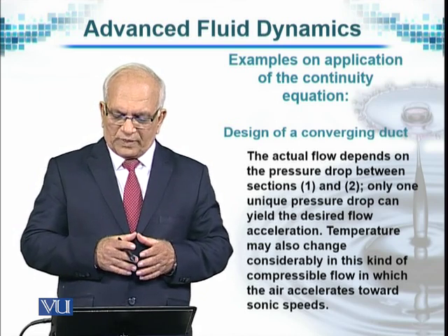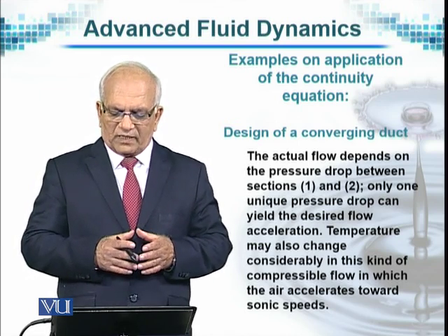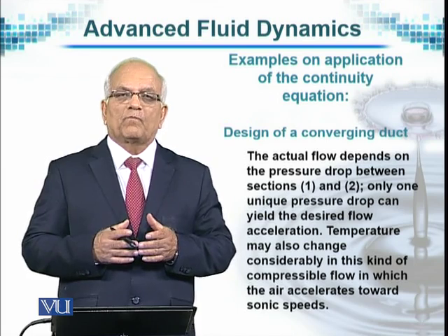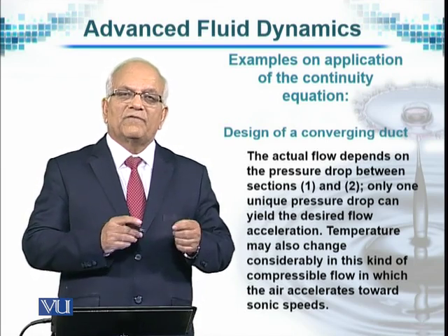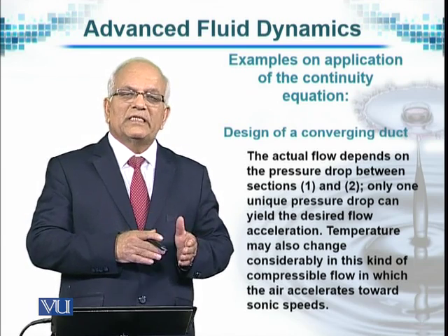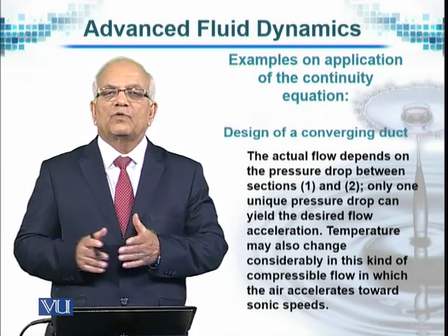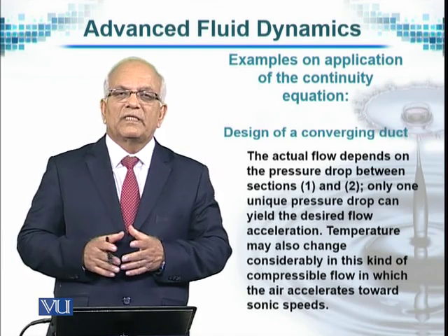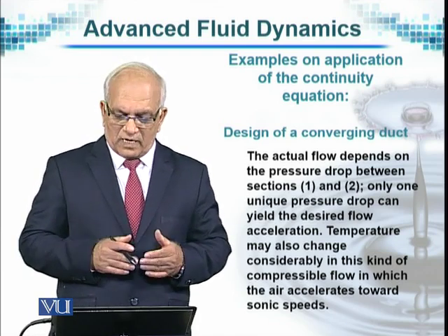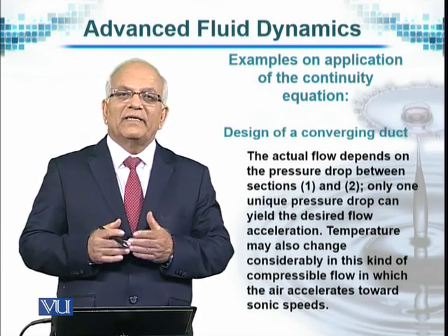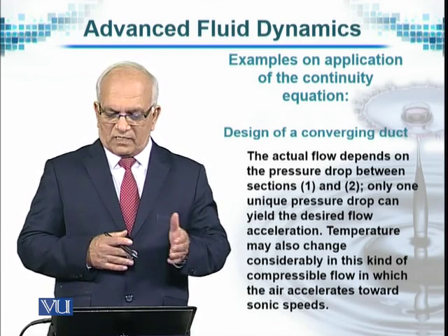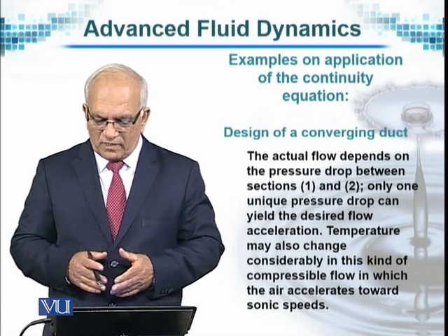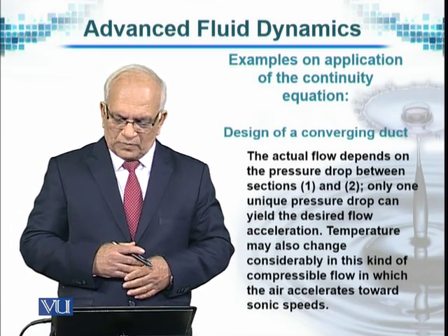Only one unique pressure drop can yield the desired flow acceleration. So this acceleration that has been given, that is the velocity u increasing from the initial point to the value that it attains at exit, is also linked with the density decreasing in a linear manner from the initial point to the point at 2.